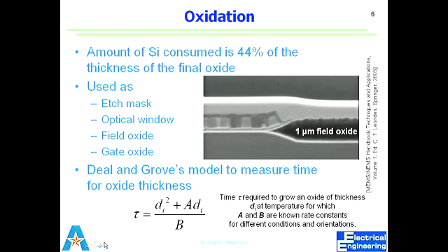What's the optical window? Is silicon dioxide transparent? Yeah. Next Wednesday you should be able to see that. I forgot, I should bring some wafers. It's the other type of mask. It's called a hard mask. The other one we just call a lithography mask, which would be photoresist.